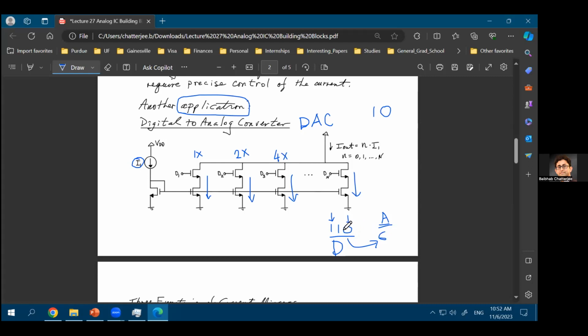So your LSB size is half of that of the second LSB size, or in other words, this one, when represented in equivalent analog form, will be 2 times more important than the LSB. So that's why it's called the least significant bit. The LSB is least significant. The next bit will be second least significant, and so on. And the highest bit will be the most significant. If you have to assign weights in binary, you do a binary weighted representation, right? So this is 1x, 2x, 4x, and so on. So what we are doing here is exactly the same thing.